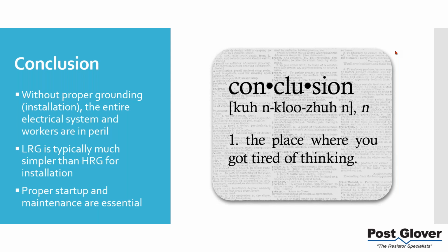Yeah, so depending on how you wire those up, you are going to be having extra capacitance on your system. The short answer is, can you hook it up delta or phase to phase? Can you hook it up line to line versus line and neutral? If the answer is yes, that's the best way to go. Otherwise, you're just going to have to deal with that added capacitance and make sure that it's still low enough to be able to use high resistance ground.